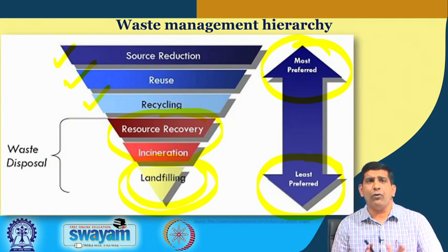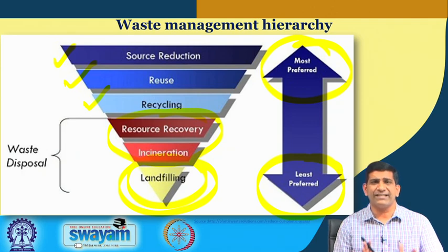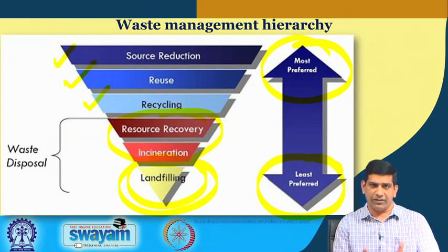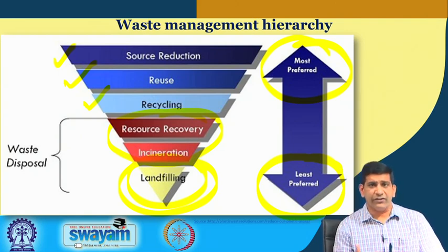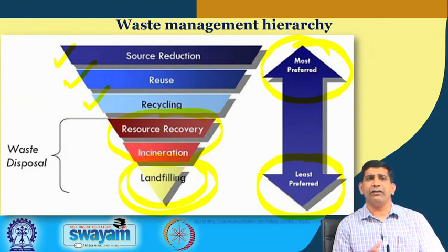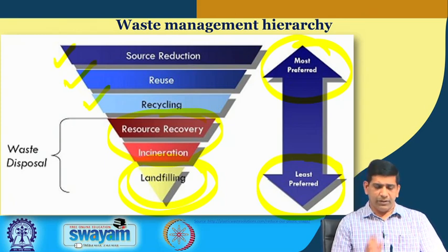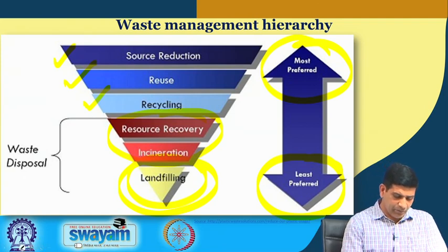This is how waste is typically managed, and since plastic waste is part of the municipal solid waste, in plastic waste also we see a similar hierarchy. We see more and more plastic going to the landfill, other than the easily recyclable ones like PET and HDPE, which do get recycled. Many of the other types of plastic end up in the landfill site or can go to an incineration plant as well. Only, when you have plastic in the incineration plant, you have to be careful about the operating temperature of the plant to make sure you do not produce dioxins, furans and those kinds of contaminants. That being said, let us move on.